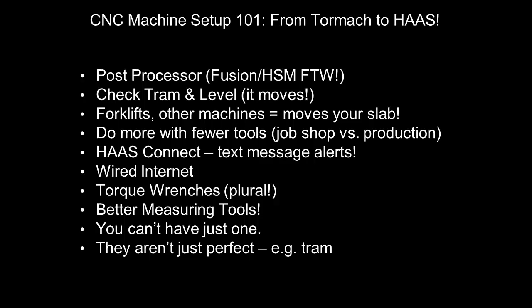You know what, this sounds like a fun contest. I'm seeing comments about how many chips people produce a day. We should have a contest one of these days for who produces the most chips. Well, the question is why. Right now I am unfortunately making some 1-inch stuff, and I'm buying 1 1/4 because it's easier for work holding, but I'm trying to change that going forward. Obviously chips are a bad thing, because it's more to recycle and it's more spindle time.